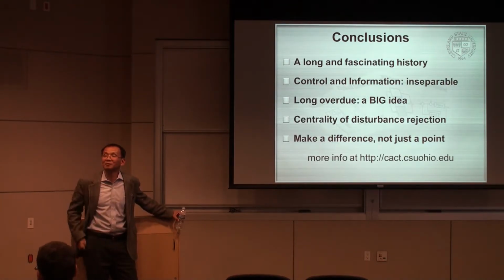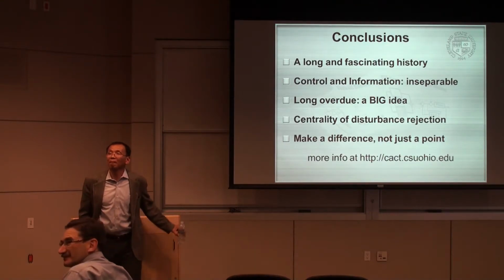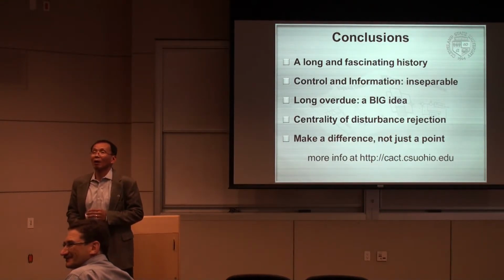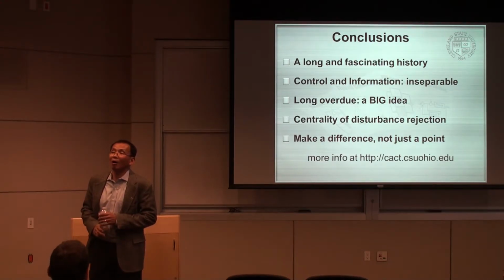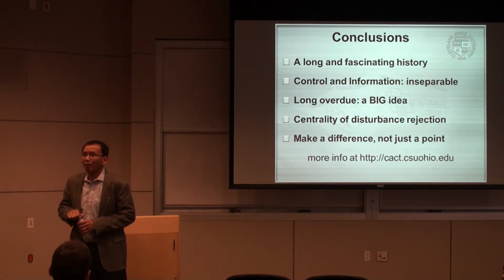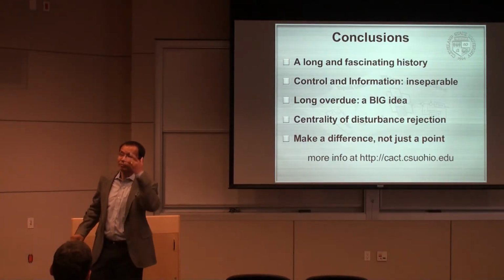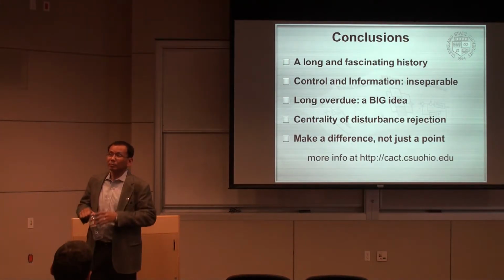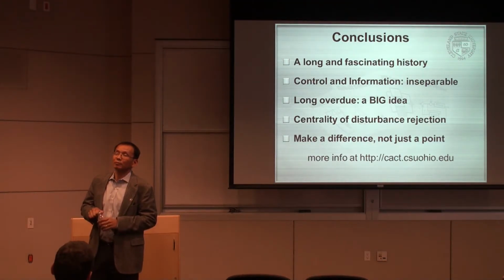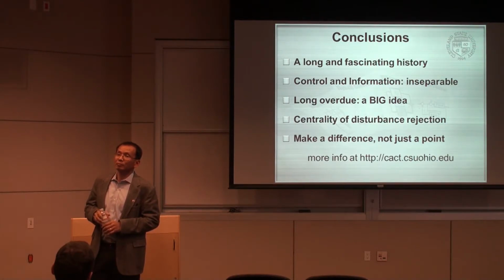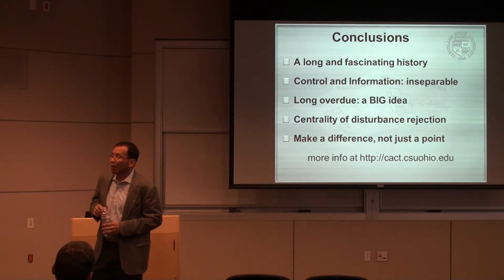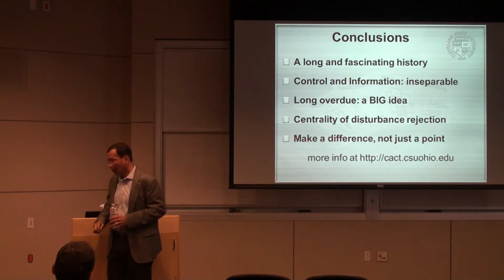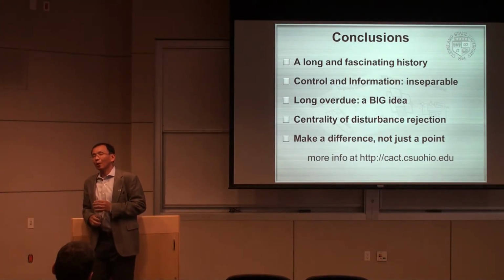I was going to say along those lines, like plant estimation, and I also don't know that I'm saying too much about this area. It seems like you basically assume a parametric expression, like a linear plant model, and then you empirically do state estimation, and find a maximum likelihood fit to the input-output data for that parametric form online. Then you base your controller on that and do kind of feedback linearization based on that active model. I'm probably butchering a lot of this, but that's what it seemed like.